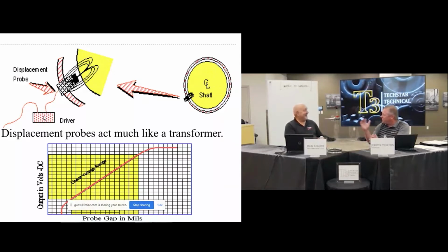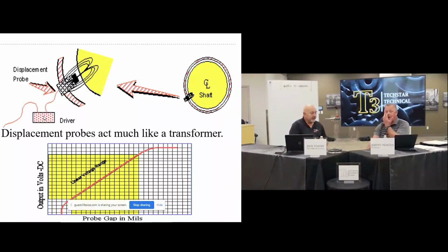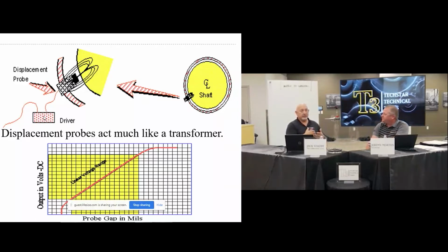Surely they roughed up the surface before they put the chrome on there. So yeah, that's a common issue that we've run across. That's right. And I've had this question asked by different customers. They will call me and say, we just received our shaft and there's a piece of green tape. Well, if you're using proximity probes, usually where that green tape is, is the probe area. Yeah. And that probe area is burnished, and I mean it's perfectly smooth right there.